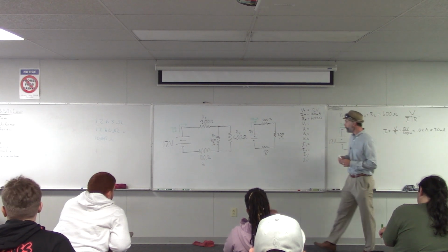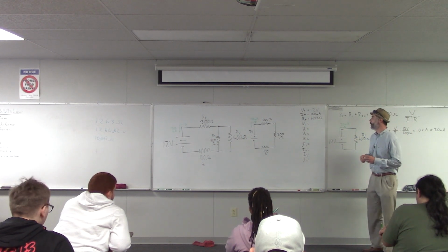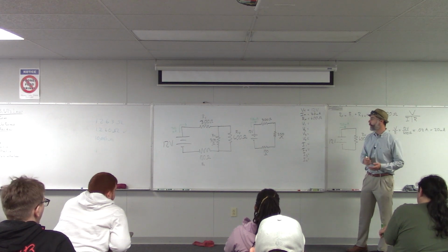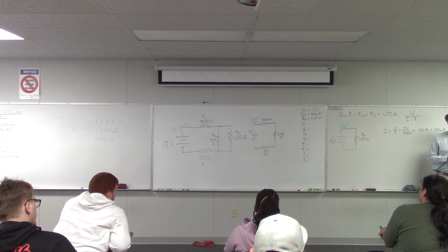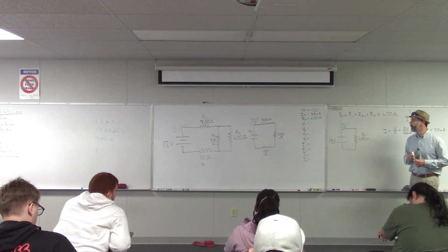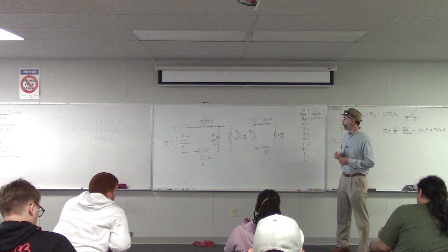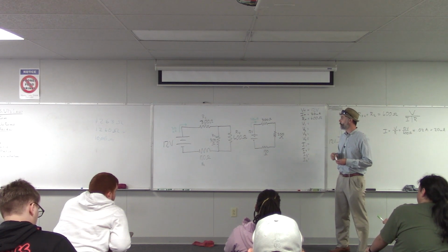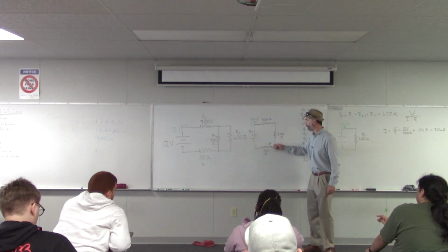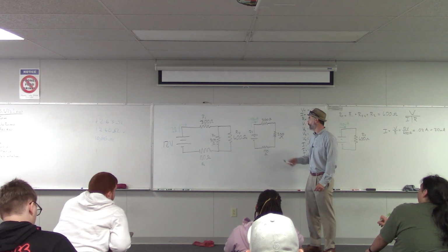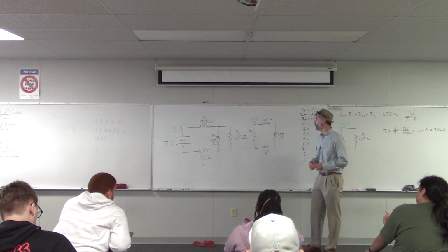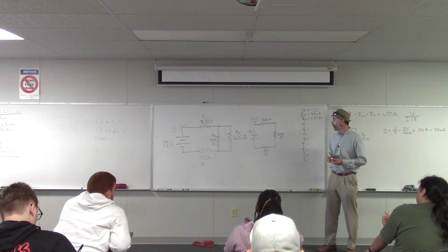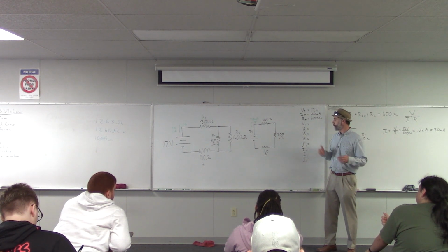All right. Cool. So now we know the total voltage, total resistance, and total current. What should we attack next? What's that? Use this to treat them like voltage dividers, right? And then find the voltage of all the resistors. Since we now know that, we can find the voltage of the top and the bottom. So yeah, that'd be an interesting way to go. So we could look at this and say it's like a voltage divider. So yeah, we could find the voltages across the resistors that way. So let's give that a try.